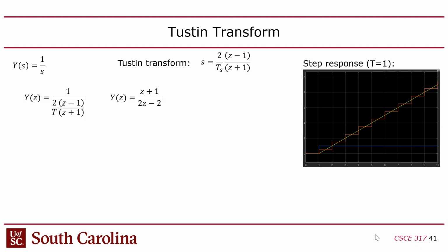What's the time step? It's how fast you make control decisions. It's how fast you look at the process variables and calculate the manipulated variable. That's what the plant does, right? It reads the process variables, calculates the manipulated variable, and puts it out. The rate at which you do that, or the time you have to do that, is T sub S.